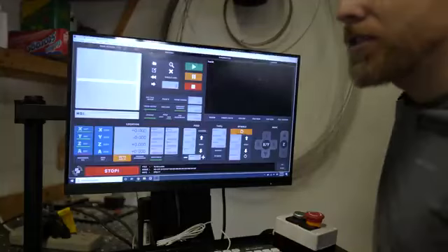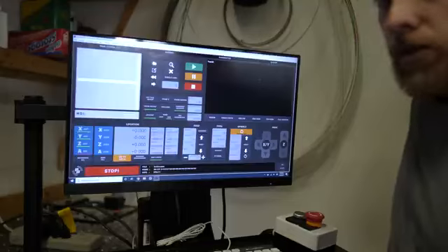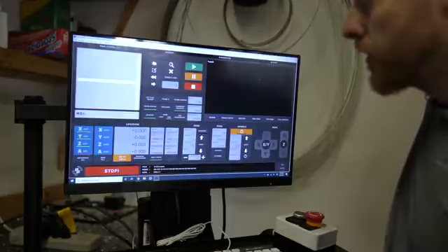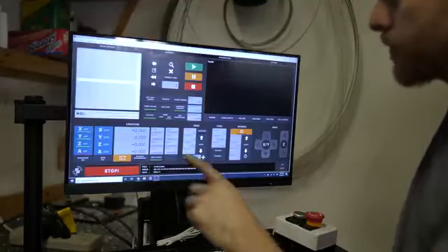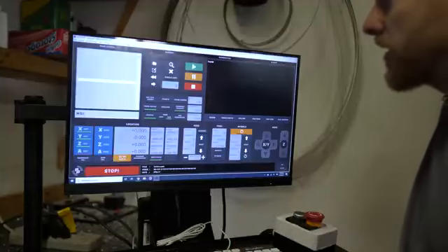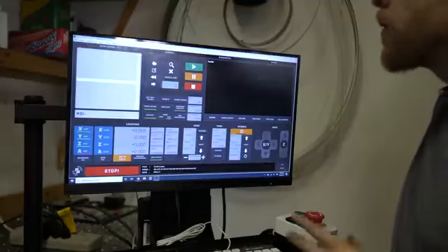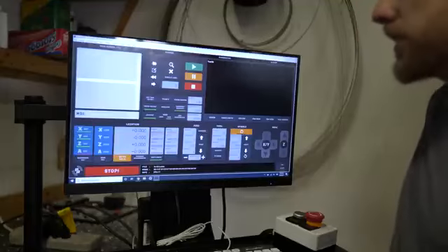I think I may change this out to just X, Y, 0, because going to 0, Z can be a little scary, depending on where your datum is set up. Your 000 for your work is. So I may change that. Actually, that's a good time to bring this up. If you see something in this that you'd like, why would you do that? Everybody else does it this way. I will definitely listen to that, and we may make some changes, because I am not a CNC expert.